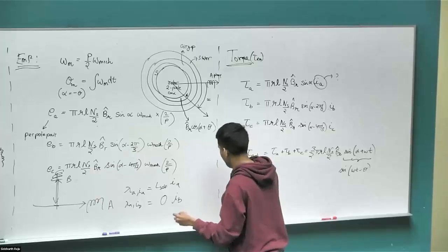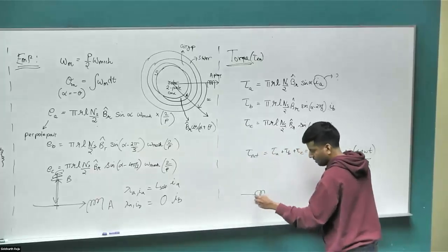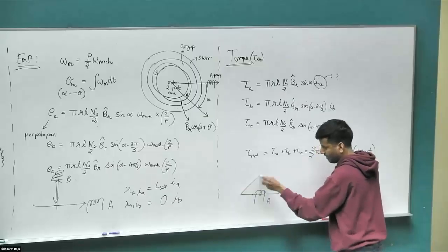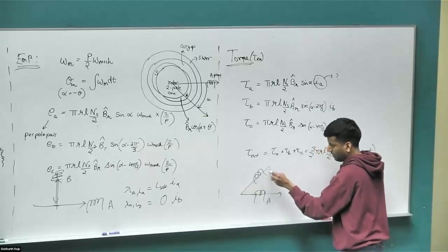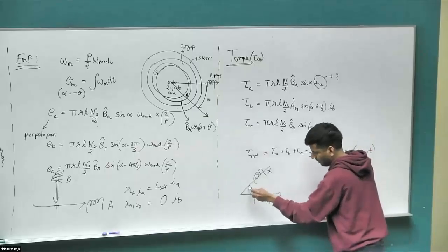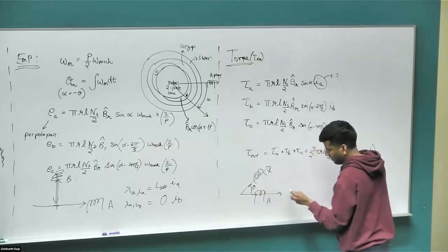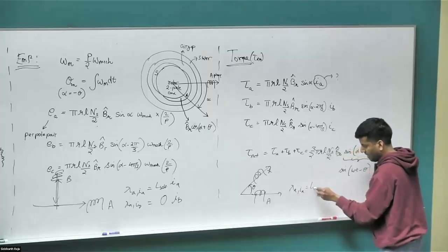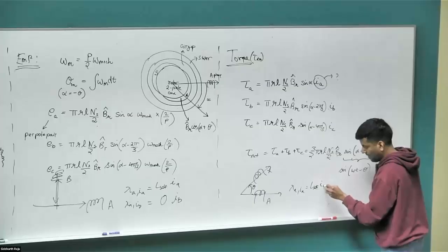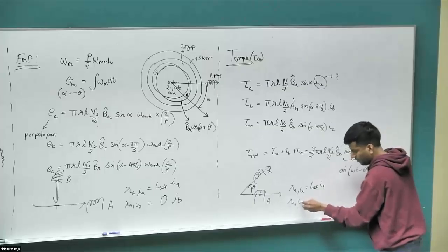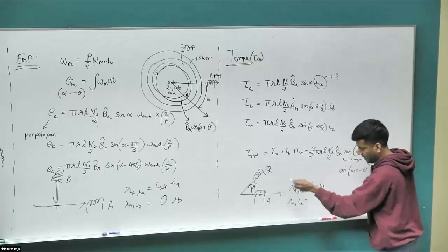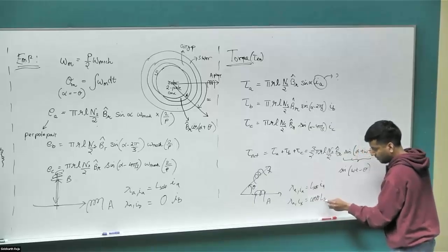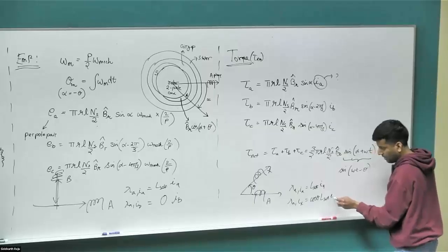So for any set of windings, let's say you have some coil, A phase here, and some other coil, some X phase at some angle theta. Lambda A due to IA is going to be L self times IA, and lambda A due to some current Ix in a coil phase shifted by some angle theta is going to be cos of theta times L self times Ix.